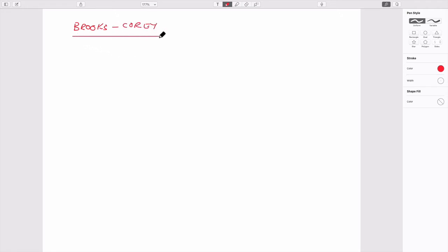And so these are the basic ideas, capillary pressure versus saturation curves. So what do I want to do? The first step then is maybe to look at one of these curves once again. If we just look at a single slither of this, as we've done before, we can think of this as capillary pressure. We can think of this as saturation of water between 0 and 1. We can think of this as volumetric moisture content between 0 and porosity, I suppose, as we've just said.